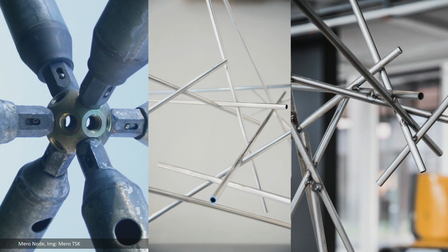One crucial element is the node. Space frames live through their node, and their efficiency and functionality is defined very much by it. Classical nodes connect in 1 point, but they require a prefabricated connection element, which, if you want bespoke angles, would require individual connection elements. And this is why I was searching for a node that can be fully integrated in the robotic process, and through shifting bars along their neighbors, this would lead to a connection where only 2 bars connect in 1 point.